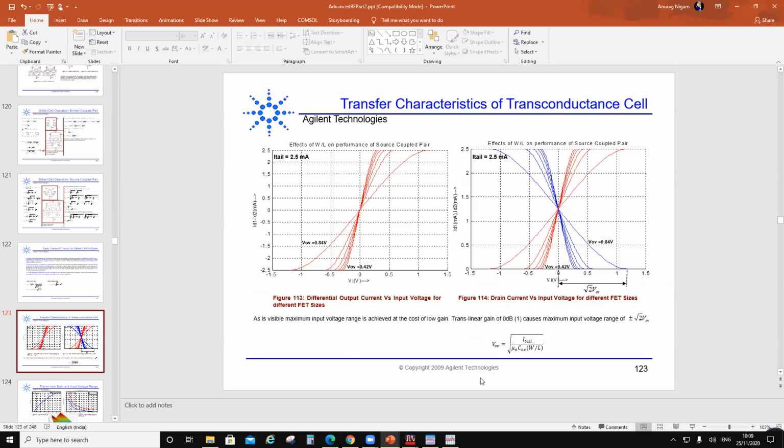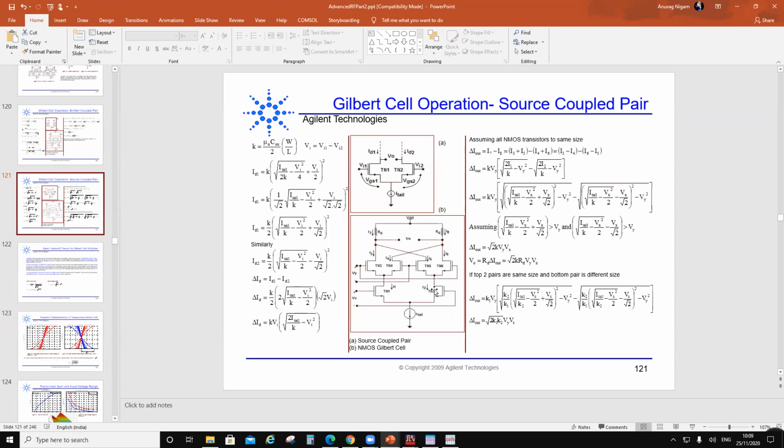If you keep on bumping the power till the transistors start acting as switches, that would be a mixer. And in that case, lots of harmonics will be generated. Now the even harmonics will be canceling out. Odd harmonics will not be canceling out.